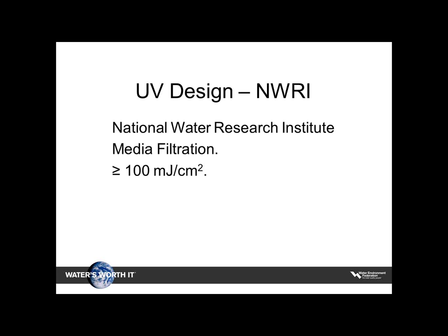So again, some of the numbers we look at: media filtration, greater than 100 millijoules per centimeter squared. That's a fairly high dose. That would typically be with a sand filter or a mixed media filter. We were having lively debates in the state about that very number. But what's interesting is they don't require a high transmittance. It seems to me that's even a little less than the old 10 States number. But maybe with that higher dosage, it doesn't matter.